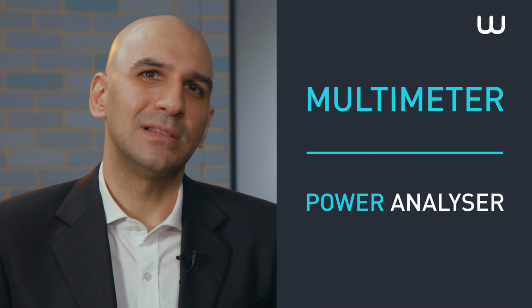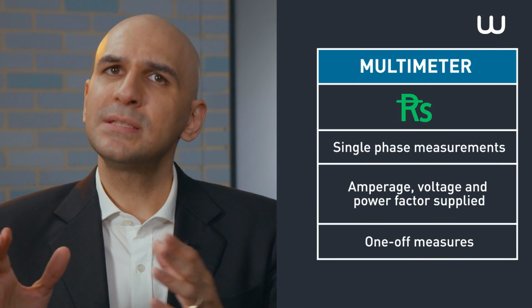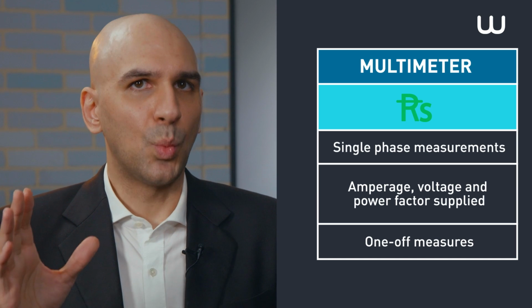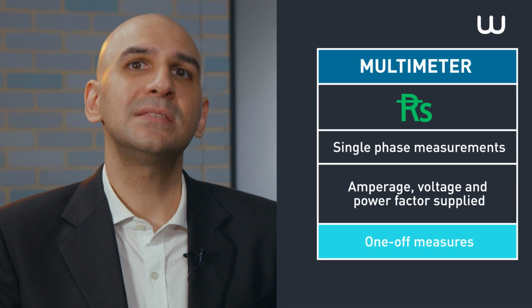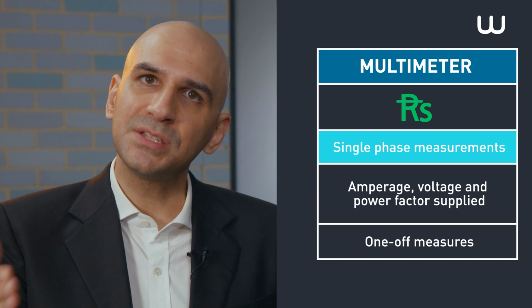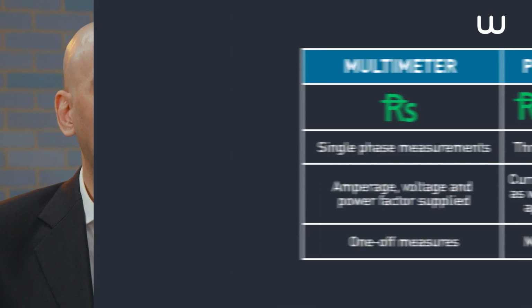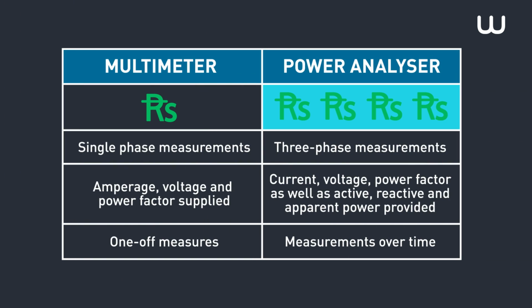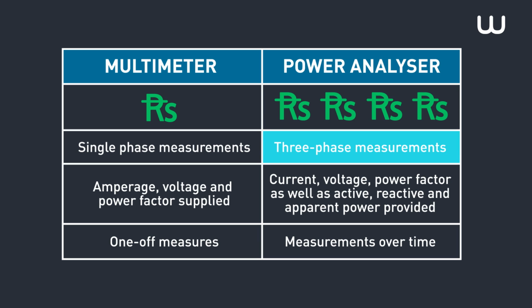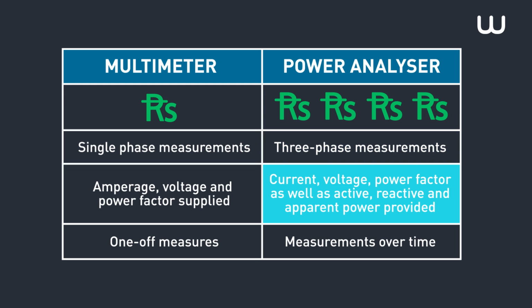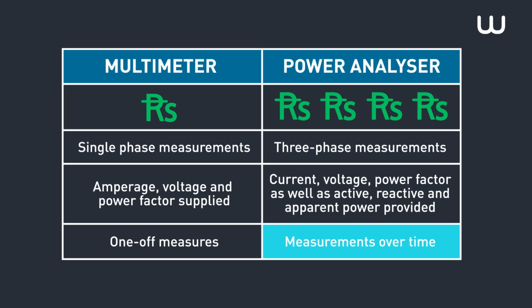What you need to remember: 2 devices are used to carry out electrical measurements during energy audits: the multimeter and the power analyzer. The multimeter is not expensive and enables one-off voltage and intensity measurements to be made phase by phase. The power analyzer is more expensive, but it can simultaneously measure the electrical parameters of each phase and automatically calculate power and energy values whilst recording the measurements at a time rate defined by the user using internal memory.